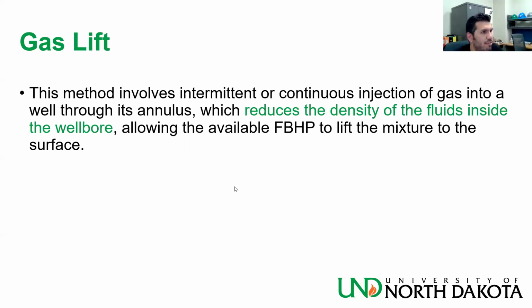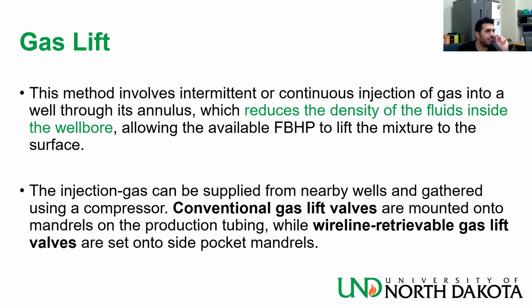The aim of it is to inject gas inside the wellbore at certain points, have it mixed with the oil inside the wellbore and make it more gaseous, decrease its density, and help it move up. The injection gas can be supplied from nearby wells and gathered using a compressor.